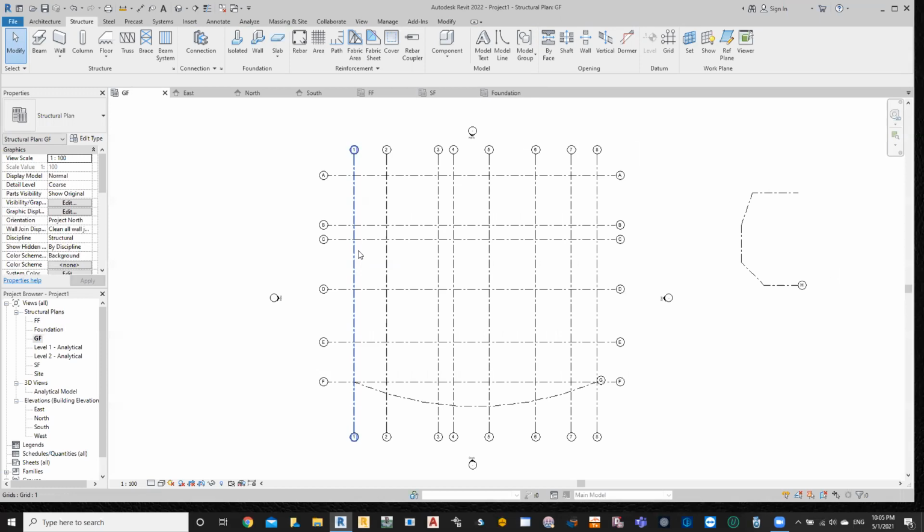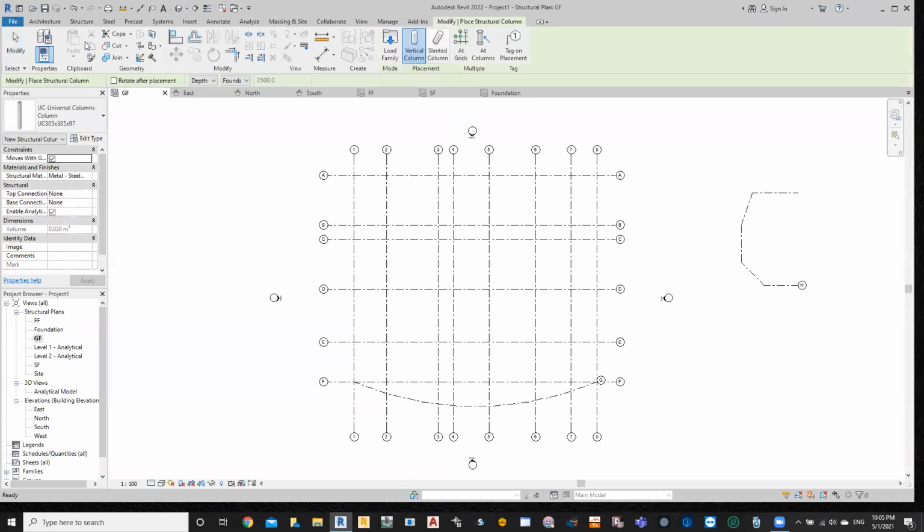Yes. Okay, now after doing that, we normally start with the columns. Once again, you should not use architecture, you should be using structure. So we're going to go for the column. Let us use concrete. Leave the section now, the section will be modified later.